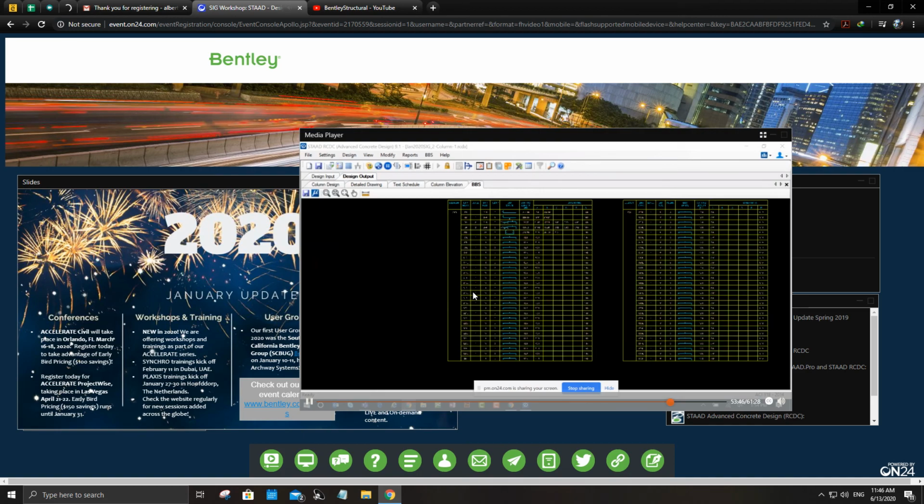That being said, I tried this yesterday, and it would still bring them over to RCDC, still define them as combined walls. But if you're worried about mesh density and joining nodes, you're either going to want to create one wall first and then create the next one, or choose the same mesh density, which is probably what I would recommend the most.